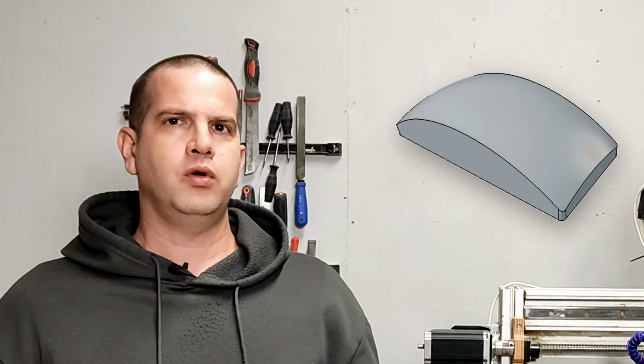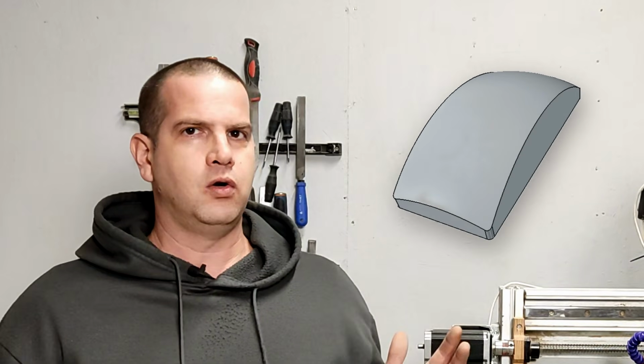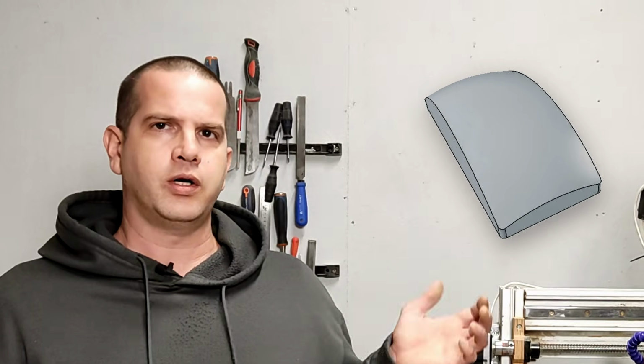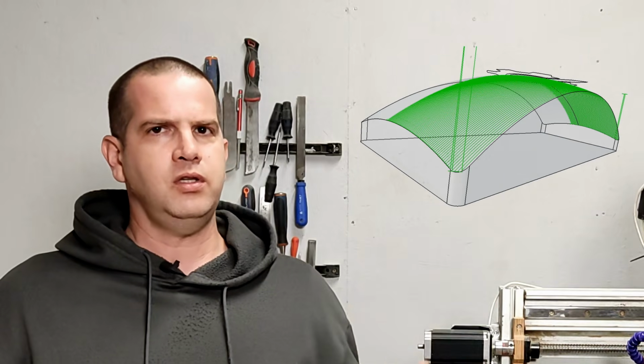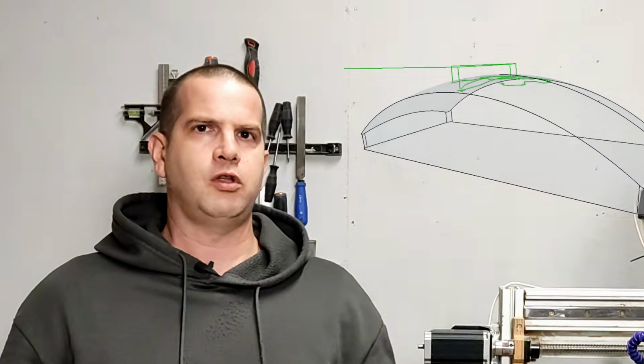In this video I will show you how to model this paperweight in the Part Workbench, how to import the SVG logo and adapt it in order to work in the CAM workbench. I will cut the outline using some tags to hold the stock in place. I will show you how to mill the top face using a 3D surface operation, how to set up the engrave operation, and the most important thing, how to make it follow that curved top face.